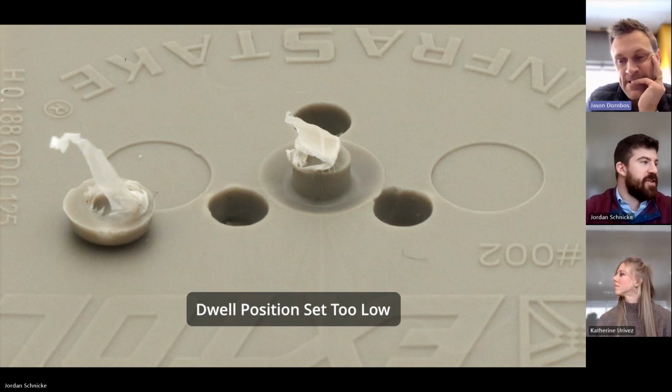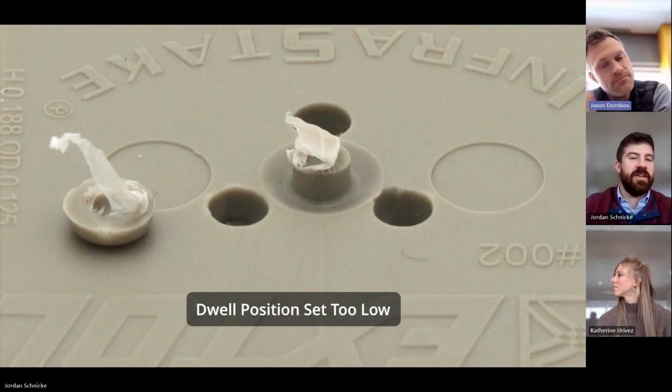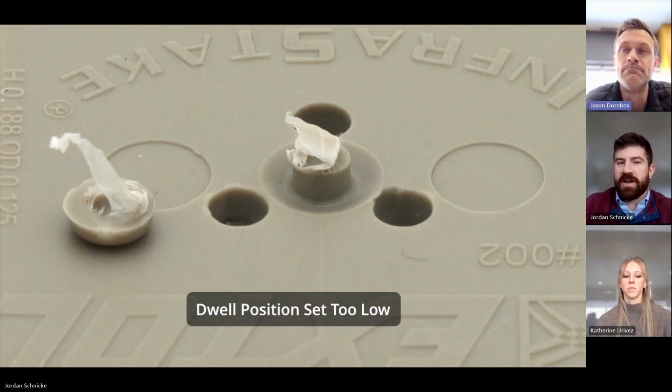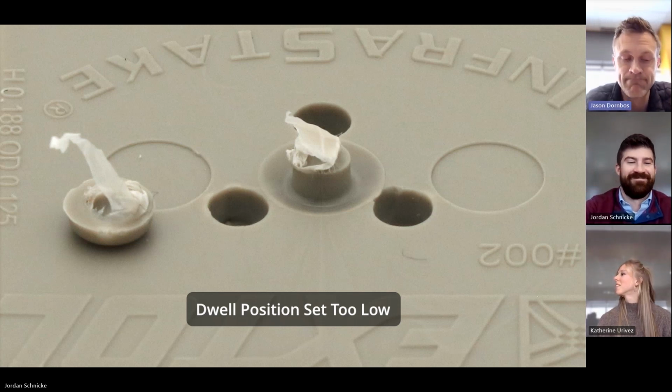I think the end result with this type of application or setting is pretty easy to understand based off the image you guys are seeing, but it's not always going to rip that off. More than likely, in most situations, you're just going to see a lot of flash or the module buried into the mating component. Like if it's plastic to plastic, you'll see this module just bury into the actual part. Which is bad. That will create more sticking. And maybe ruin your Smart Release module. Smart Release will not solve that issue.